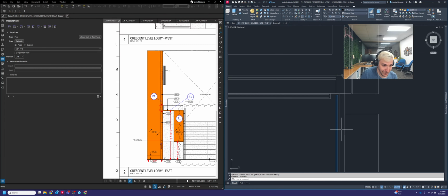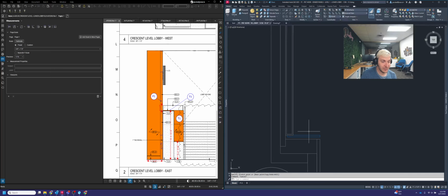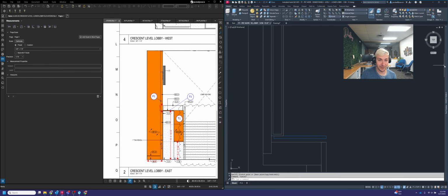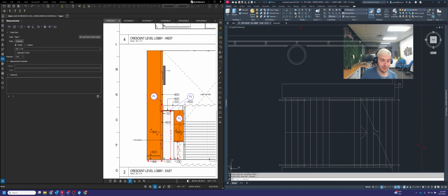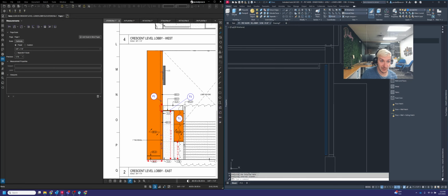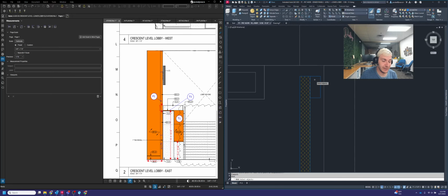Make sure that our plan view does reflect those same exact changes there. We are going to do what we did before with our section view. We are going to hatch our panels in the plan view to represent that these are our panels here. So I'm throwing in the MDF hatch, just like we used on our panels below in the section views. And then I need to throw in the full depth reveals. Just like what we did on our section view, these full depth reveals, we're going to use the rectangle command. We're going to go 0.75 thick, 1.5 tall, and we're going to use the move command to place these exactly where they need to go.